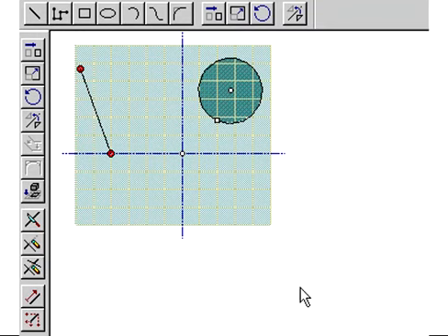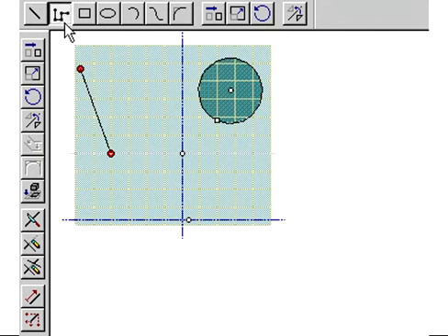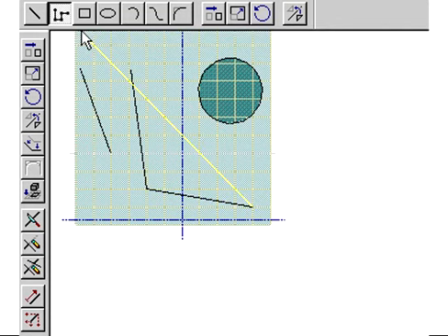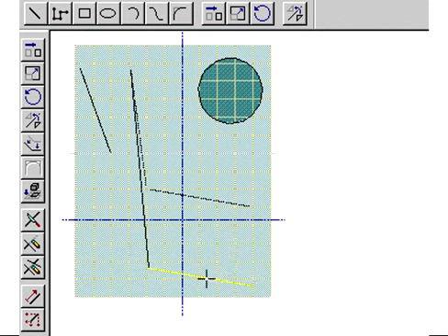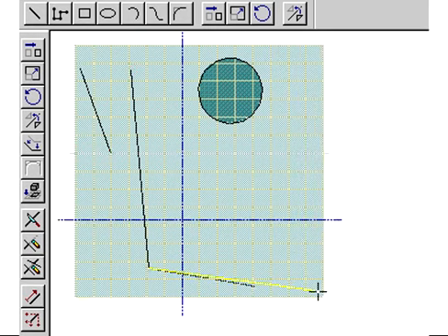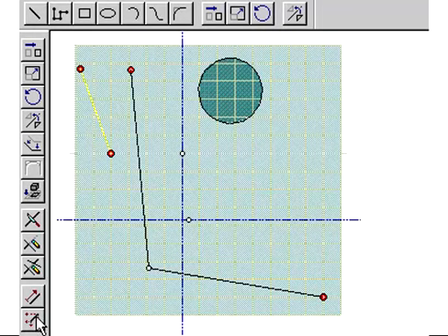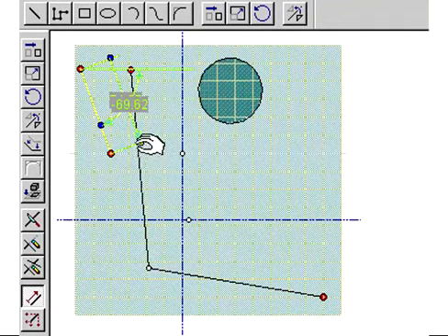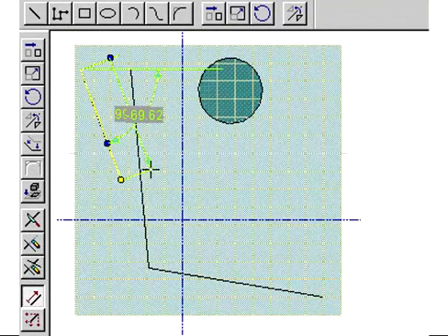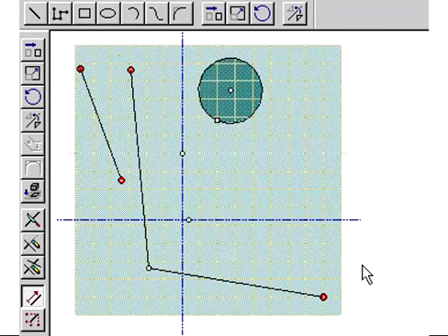When you work on the 2D drawing surface, you can drag the horizontal and vertical axes to position them on your model. Use the 2D drawing tools to create lines, circles, and other geometry. To move a line or other element, select it and drag it. Drag an endpoint to change the size of a 2D item. To see endpoint coordinates for your drawings, select the Show Endpoint Positions tool. To see angle values, choose the Show Curve Dimensions tool. To change the size or angle of an object, select it and drag the blue handles.